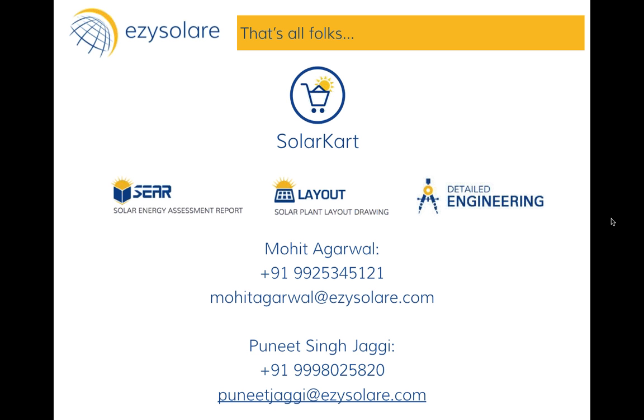A hybrid solution might be possible. We do not encourage that, but a hybrid solution which might be possible, that means you can calculate your loss because of an uptime guarantee. You can also calculate your loss because of a generation guarantee. And after that, you calculate which is the higher of the two, and you can ask for a compensation for that. But it is not scientifically correct to actually even ask for an absolute generation guarantee from an EPC contractor.